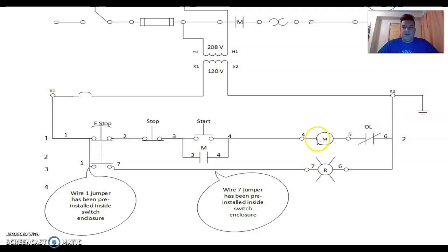But essentially, if the control relay is energized, that means that the e-stop is not being used, and everything is safe, and the control circuit below will function. When you press or activate the e-stop, it will break the X1 and X2 power rails and basically disable the remainder of the control circuit. So we like to call that either a safety relay or a master control relay. There are different terms that are used.